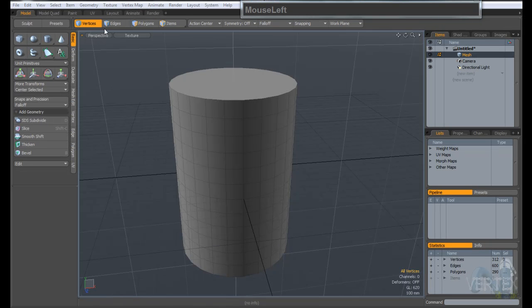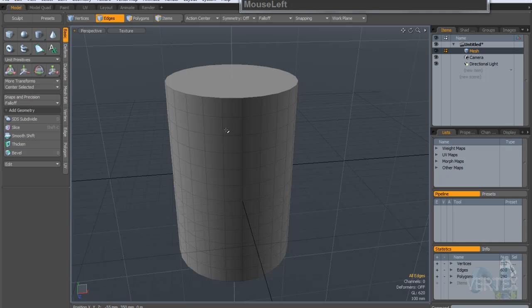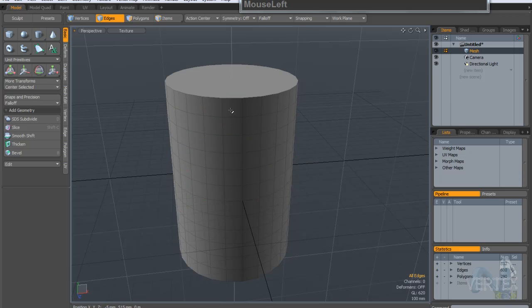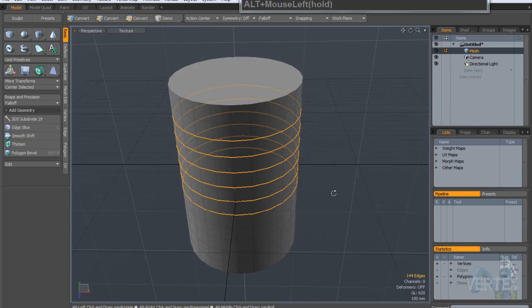Let's continue our selection methods. You can select one edge to give a direction. Just hit L on your keyboard to get a loop. Shortcut L. You can select one or more edges and hit L to get a loop. You can select a loop just with a double click on an edge. Hold Shift, select your edges, hold Shift and double click on your edge, select all.